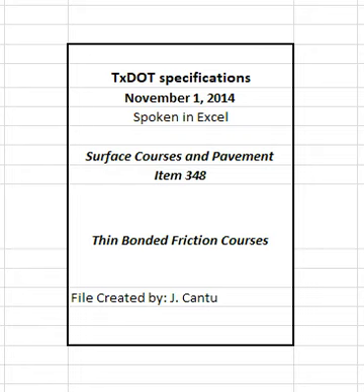The engineer may allow alternate methods for determining the asphalt content and aggregate gradation if the aggregate mineralogy is such that TX236F does not yield reliable results. The engineer will require the contractor to provide evidence that results from TX236F are not reliable before permitting an alternate method unless otherwise allowed. Use the applicable test procedure as directed if an alternate test method is allowed.